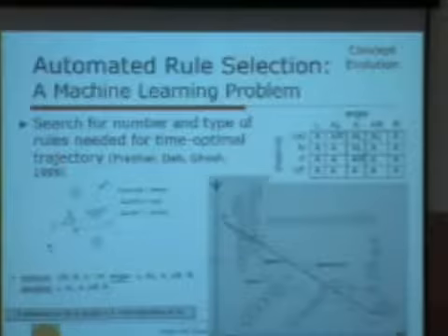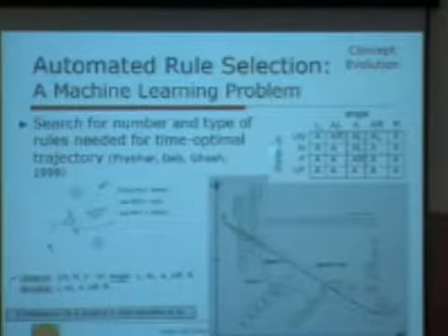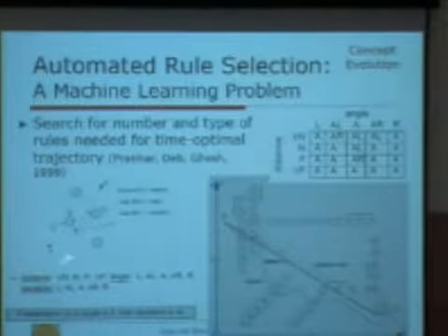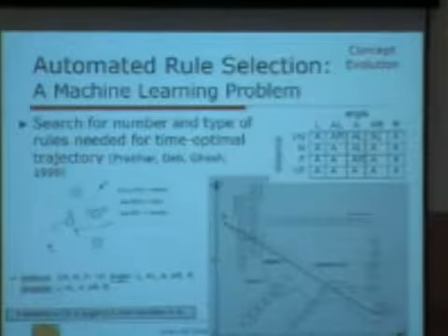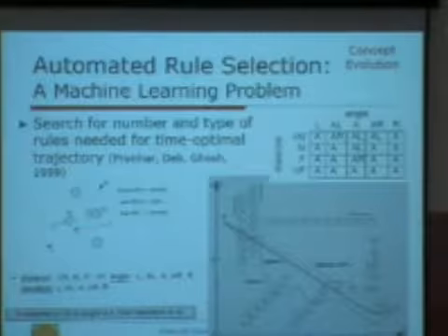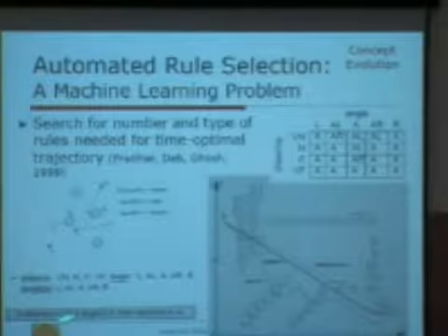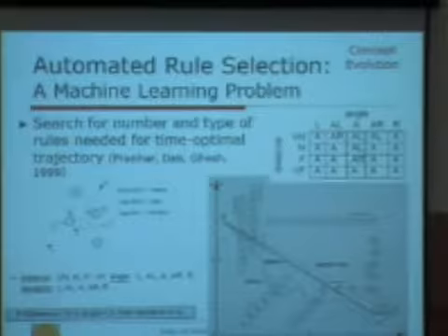One of the things that we did lately was this robot that you have seen. You have quite a few obstacles, and then you have to decide, depending on the input scenarios, how you want to turn and things like that. That's where you use a set of fuzzy rules. We are not giving it the solution, but we are saying what kind of rules it should use, and we don't care about the exact angle or exact distance of the obstacle from the robot. So we use a fuzzy idea. For example, one of the rules could be: if the distance is very near and the angle is ahead, then the deviation of the robot should be ahead left, or things like that.